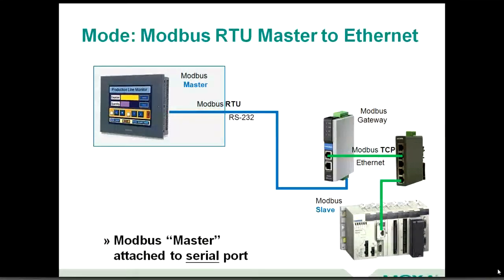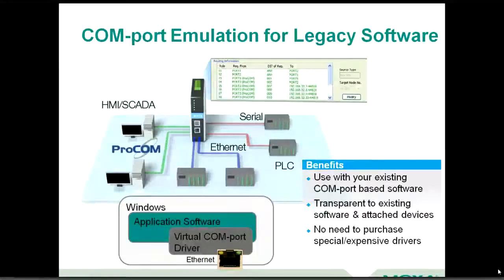Another thing, and we find this today, even though we see a lot of folks that have moved to Ethernet, there's still legacy software out there that can only address a COM port. If that's your situation and you have software that can only address a COM port, we're talking about getting things on Ethernet, so how do you get that software to work across Ethernet? Well, we have a technology called a virtual COM port, and that virtual COM port technology basically consists of a Windows driver.